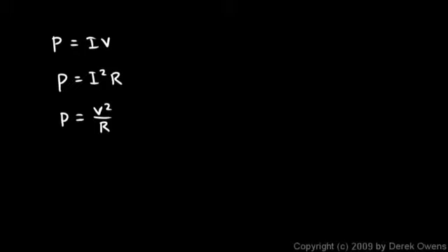And you might ask, well, if you want to find the power, which of these equations do you use? And the answer is simple. If you're given the current and the voltage and you want to find the power, use this equation. If you're given the resistance and the voltage, use this equation. If you're given the resistance and the current, use this equation. So, as is typically the case, you think about what you know, and think about what equations that you know are the case that can apply in that situation.